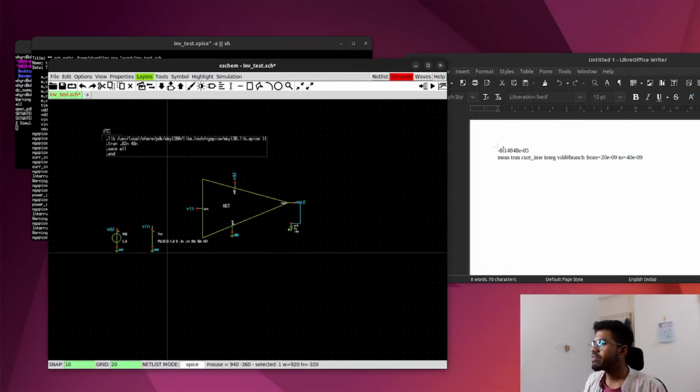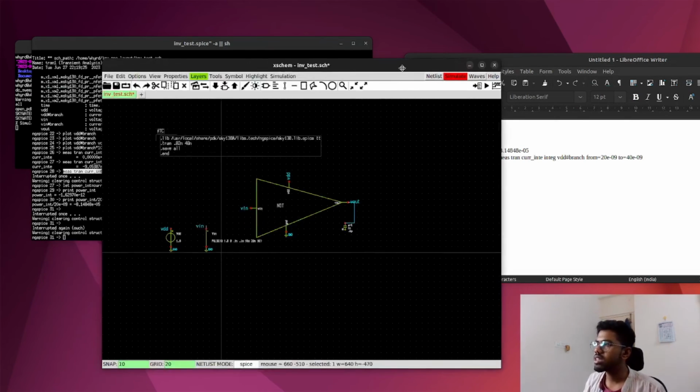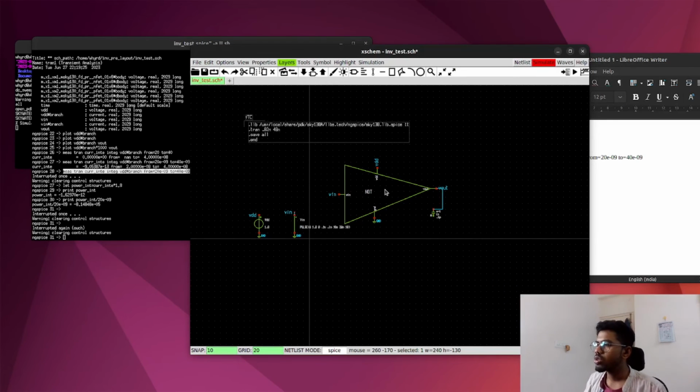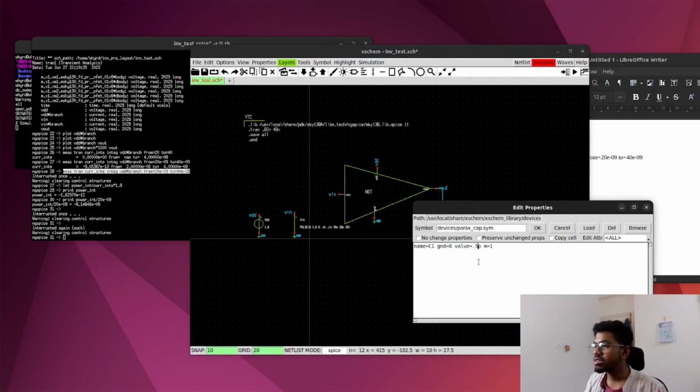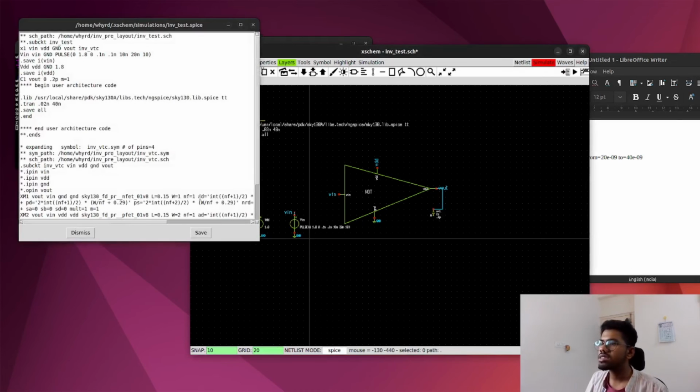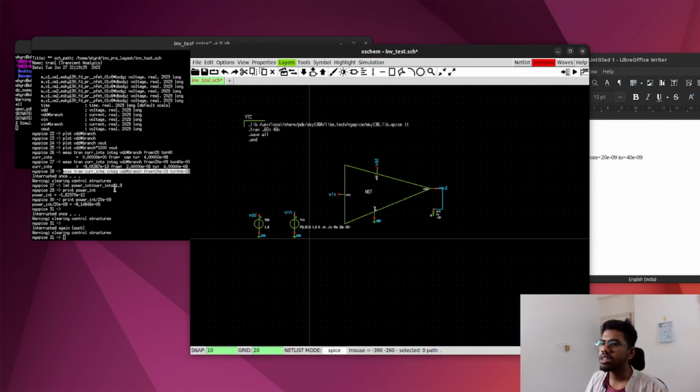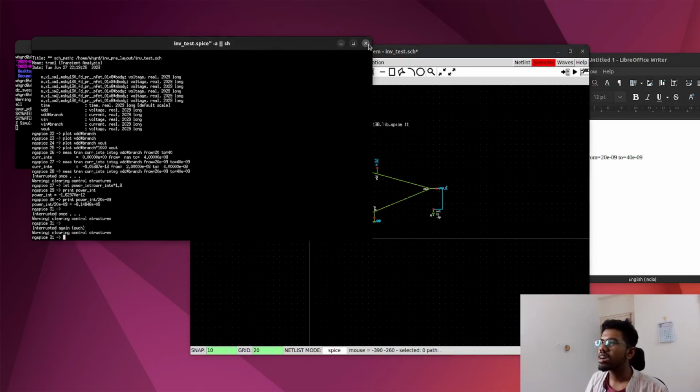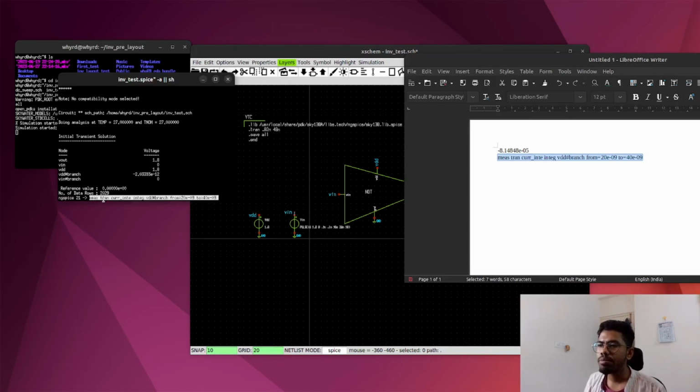Okay, so I have written everything here. This is your average power, and this is to speed things up. So let me do one thing. I'll just reduce this capacitance here. If I reduce it to, for example, 0.1 picofarad, okay, netlist, save, simulate, simulate, and then paste this.